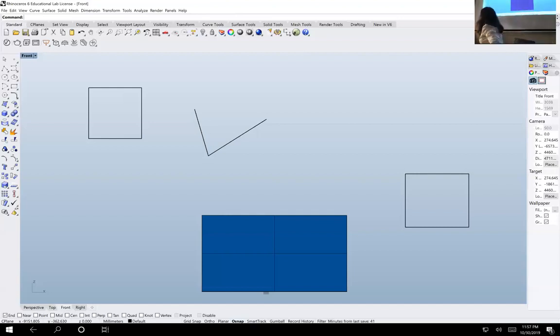Oh, this is end. This is a point. This is a meet. Okay, never mind. Once you get further, you open your own interface, then you will read what they are. I normally snap to the end, or for this case, I will snap to the middle point, yeah. So I'm going to start to draw a curve. Because I snap to the middle point, see when my mouse is pointing somewhere at the middle, here is the middle of this line. You see it identifies as middle, so it would snap to it.